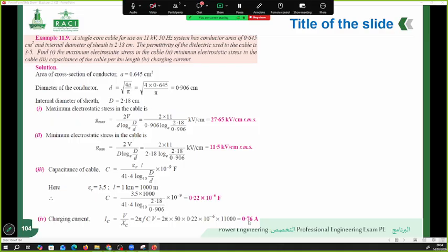So this demonstrates that even in the absence of load, underground or long cables draw a capacitive current, which is an important consideration in power system design, especially for voltage regulation and reactive power management.